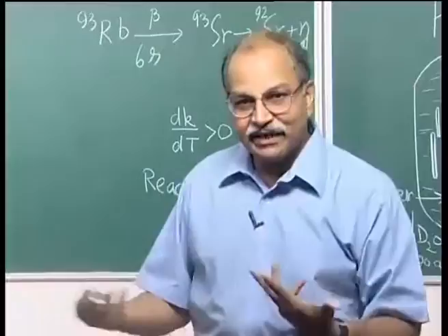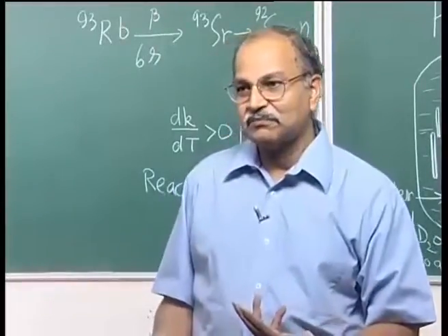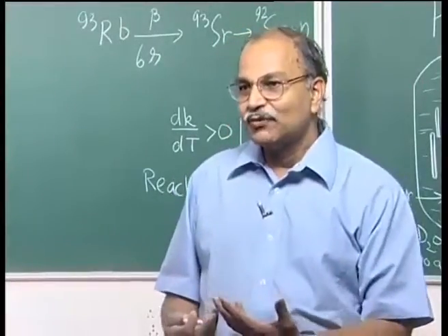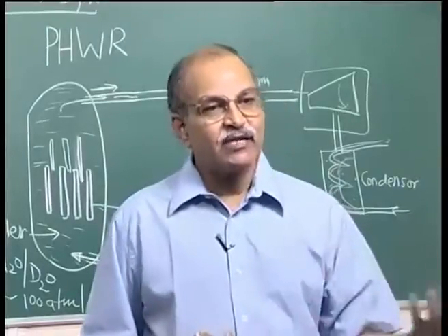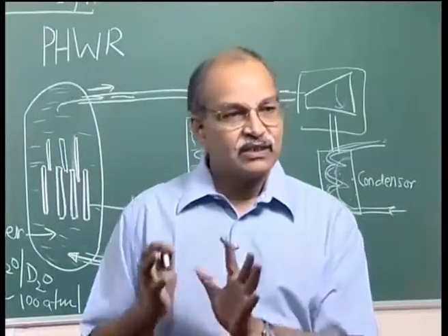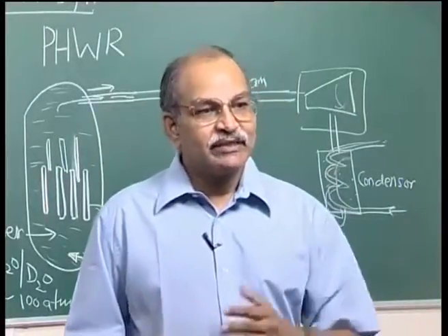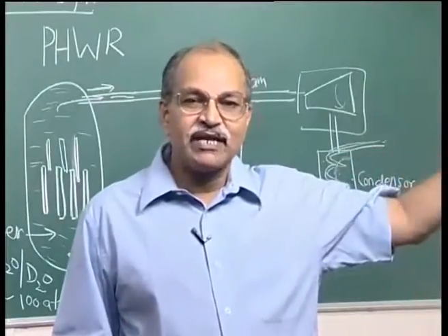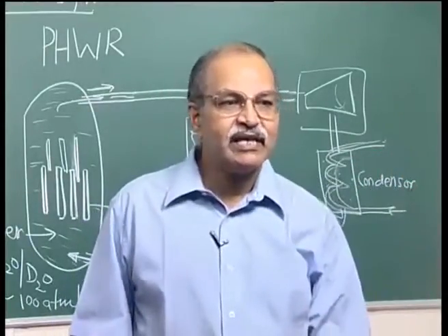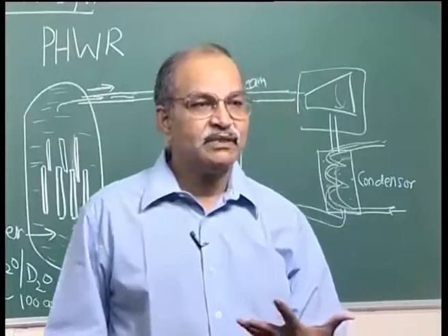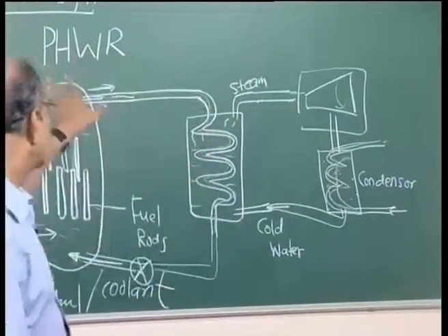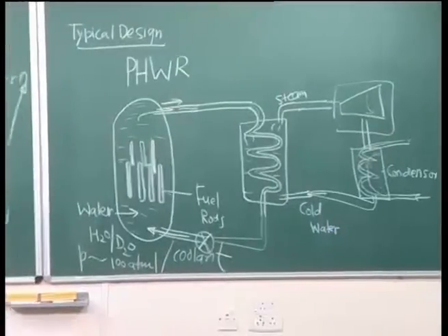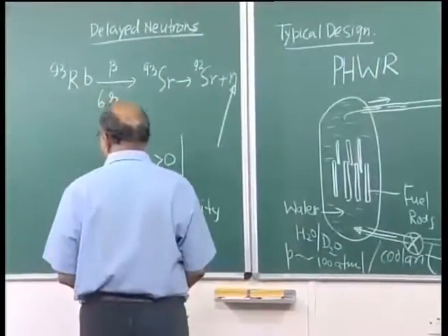So, it is a trade off. Heavy water is costly, one has to make heavy water from light water, that involves its own complications, but then this enrichment of uranium can be saved and natural uranium can be used. So, that is the difference between PWR and PHWR.